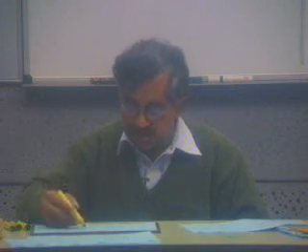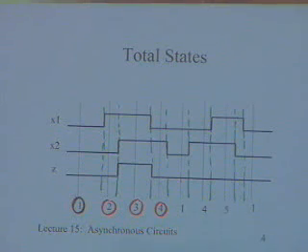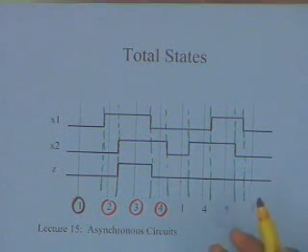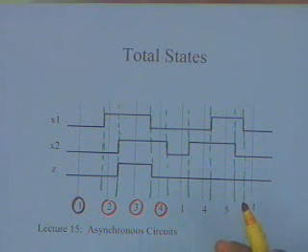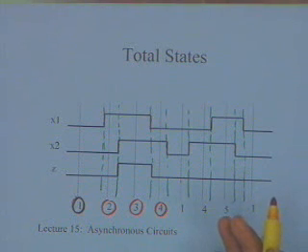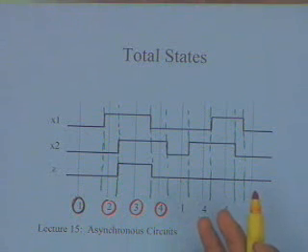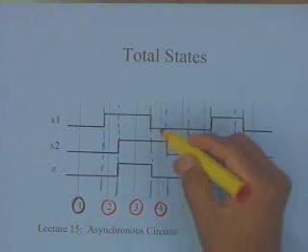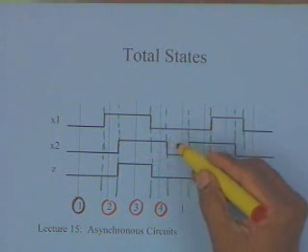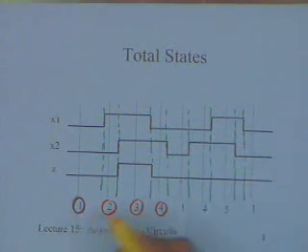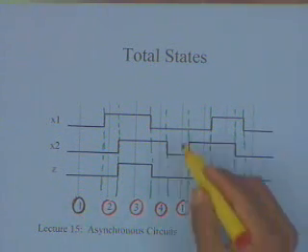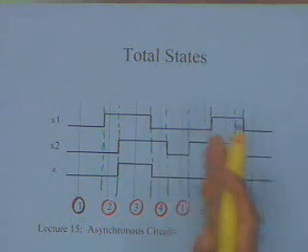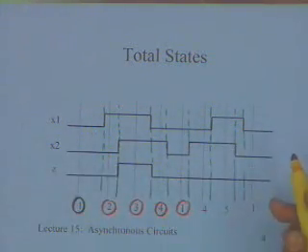So this numbering of the states is important because you should not have more states than what is required. Remember the even odd problem. When you are doing a synchronous state machine, you only needed to capture whether the number of ones till now was even or odd. You do not have to keep on storing all the ones. Similar situation exists here. Once you reach this 0 0, I am marking this stable state as the same as this one, because everything else is now going to be exactly identical as I was before.